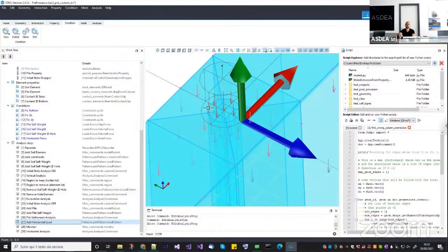You put the pile, you perform the analysis. When you are done with the pile and the settlement analysis, you remove the hole. So it can be done. If you had a crash, the crash was probably the same. When you try to remove the inner elements and the inner nodes, the load was still there, and that load produced a kind of an error. If you want, actually, we can try to simulate it later on. Okay, so I will try just to switch the order of the excavation, and we will see if it works.